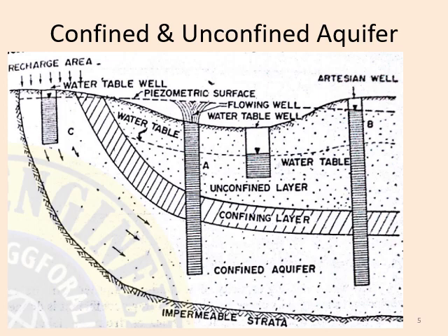Like A, B or C, it is not going to the confined aquifer, it is only restricted to the unconfined aquifer. So this is also named a water table well, like here also a water table well, and some water will rise in the well from the circumference of the well. When we pump out this water, a depression forms, and we can see the decrease in the pressure.